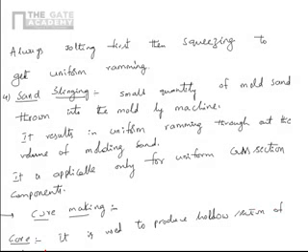To understand this, suppose I want to produce a cubical shape component. Then I can use a solid pattern, insert it in the mold and prepare an empty cubical cavity, pour molten metal into that, and you will get a solid casting.